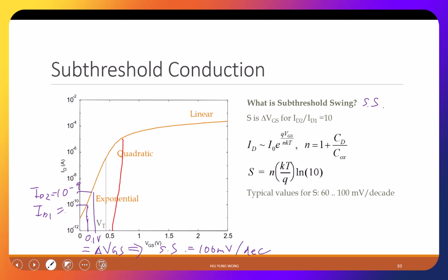For some, we call it subthreshold operation. Some people try to bias their transistor in subthreshold, which consumes super low energy. Although they are slow, they are very useful, because some equipment, like maybe the pacemaker for your heart. Yes. You don't want to change the battery, right? But now the technology is very good.